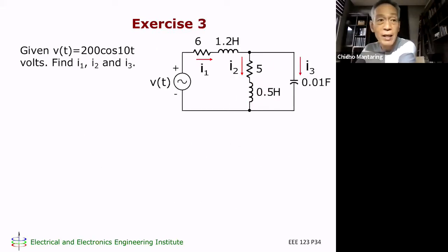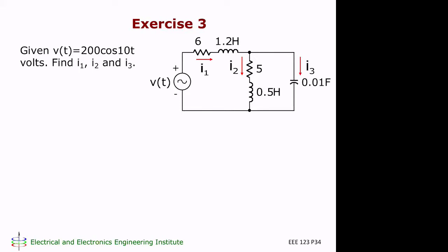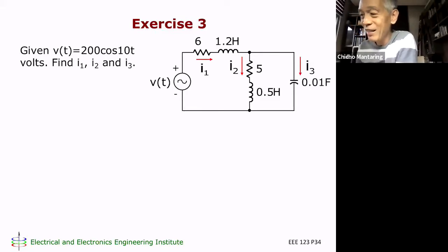This is an example of, well, there are many solutions to this. So, what is the first step? Can you remind me? Convert into phasors and impedances. Okay, convert into phasors and impedances. So you transform the network basically. Transform network.